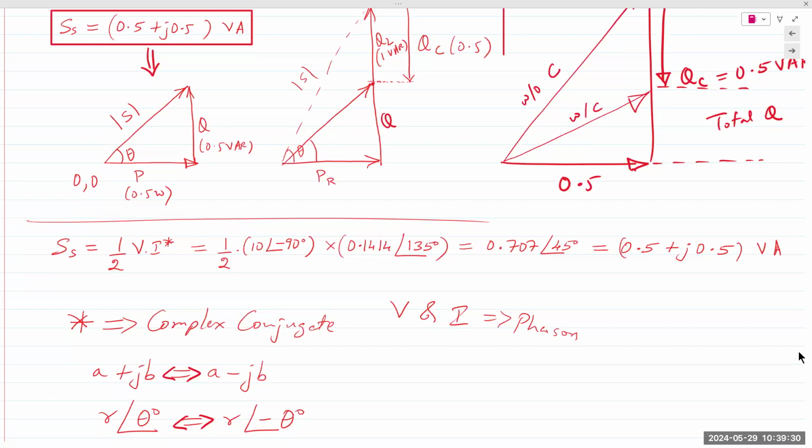Step back. The higher the amount of current, the more power is delivered. The more power you deliver, the faster it charges. So if you connect your smartphone to, let's say, a computer, it charges slower. The reason is that the computer can only supply 0.5 amps. If it's 0.5 amps, the power is reduced. The power received by your smartphone is only 2.5 watts.